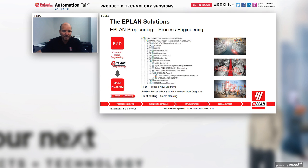The beauty of Pre-planning is that you can capture all of the data in a structured environment. So instead of using Excel sheets for your instrumentation or your signal lists, you have it directly tied to the design. When you create your PFD or your P&ID, you also have the structure defined and all of the data created. This data structure is also very similar to PlantPAx, a Rockwell solution to program all of your process controllers for process applications, whether it's batch control or various different process controls. So a data exchange would be possible, where information from EPLAN could be sent to PlantPAx, or vice versa. Interface capabilities are available in that environment as well.